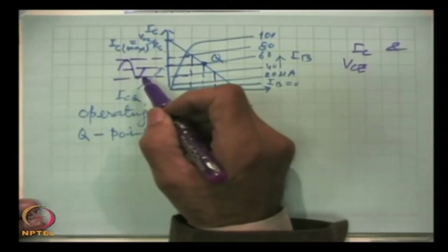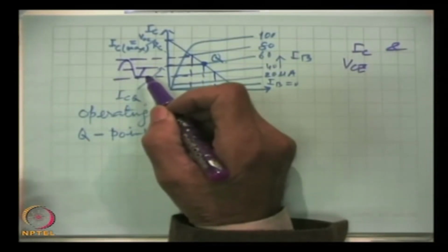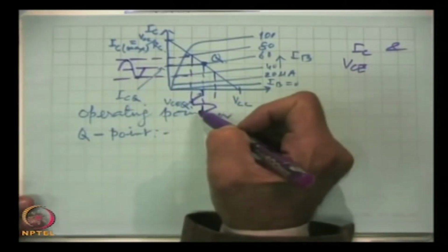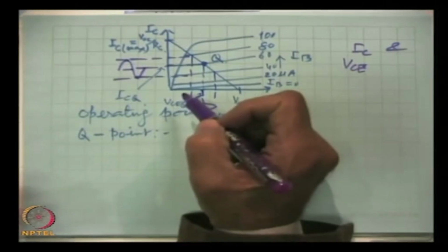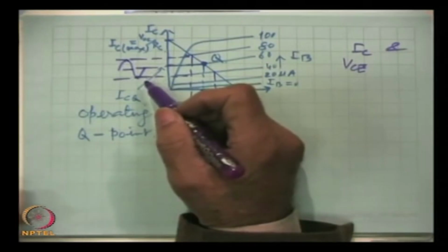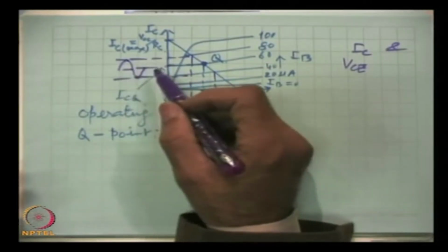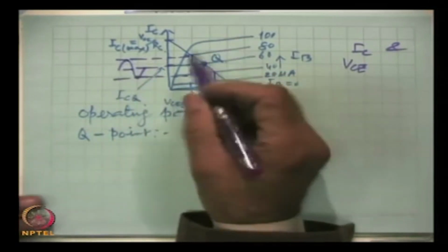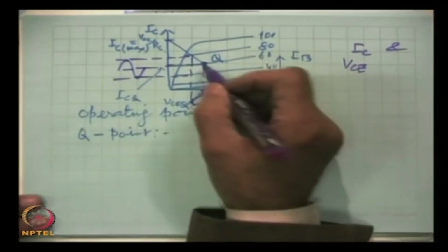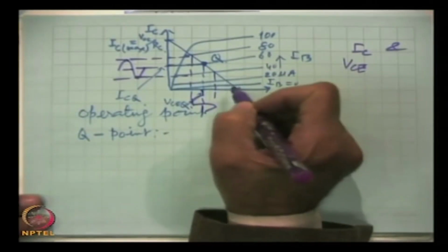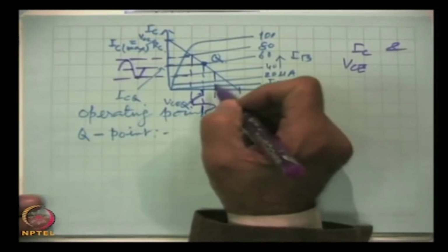We expect from an amplifying circuit that the output signal should be an exact replica of the input, and only the magnitude will vary. This magnitude here is in current form, and we will see later that this enhanced current will give a higher voltage signal also. And if this shifts towards the cutoff region, again there will be distortion, that I will make clear.